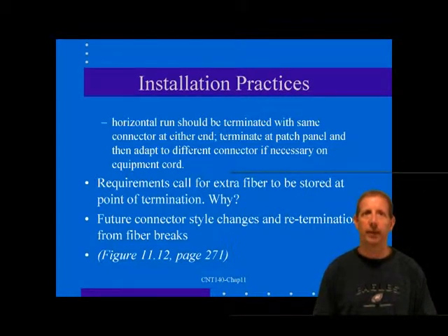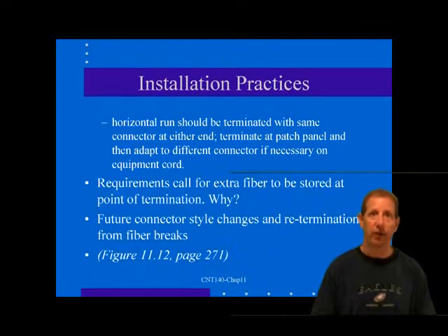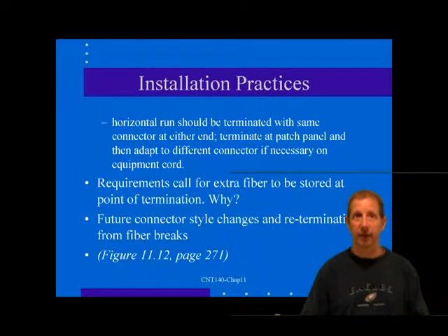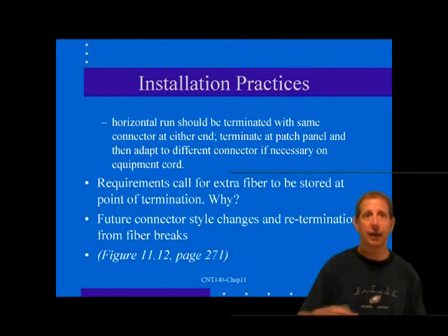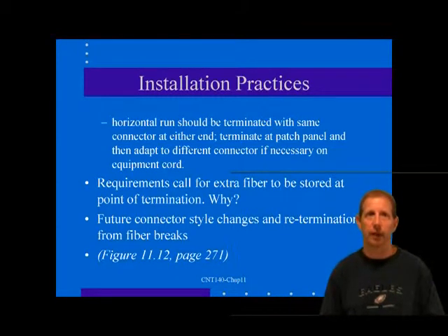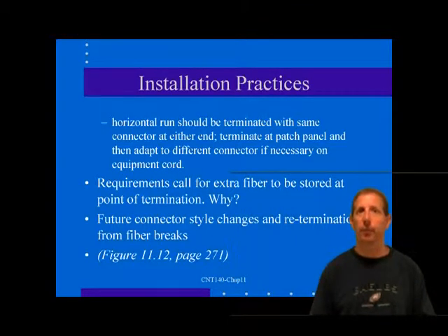for your proposed application. You should be aware that there might be significant difference in the expected connector losses between the two termination methods. For example, Avaya, formerly Lucent Technologies, one of the SFF manufacturers, offers a 0.2 dB loss expectation in their quick termination LC connector and achieves half that, 0.1 dB, with the field termination. So field termination offers better potential results, but may require more training, special equipment, and take longer to install.